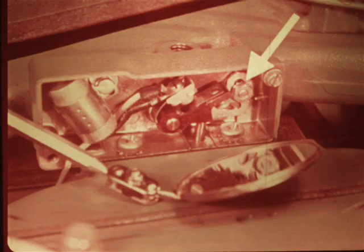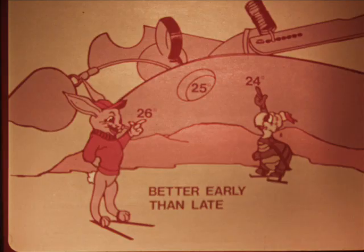If an adjustment is necessary, use a small hand mirror behind the breaker box to see what you're doing. Use a short-handled screwdriver and ignition wrench to adjust the points so the timing is right. Here are a couple of tips on timing. 1. A feeler gauge adjustment of the points isn't always accurate enough. That's why you should use the ohmmeter to measure the exact point when they break.